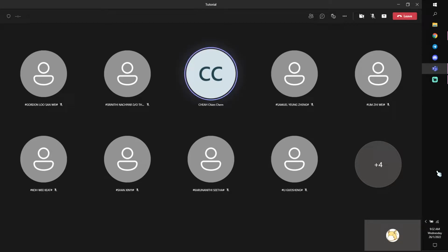In this case, for example, over here we have one unknown node voltage. And you can assign this node voltage, let's call it V. There's another node here, but this is a known node voltage. It's not unknown in the sense that we know that this is 12 volts, because this is connected to ground, and here there's an increase in potential by 12 volts.